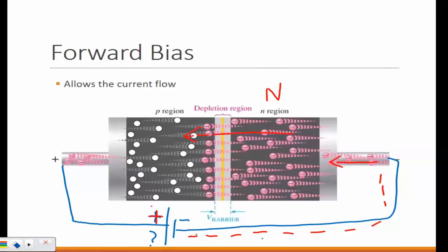Again, you can have a full current if you have at least 0.7 volts, because that will counteract the already developed barrier potential of 0.7 volts. Then you can operate it for whatever application you want. Again, we're only talking about how to use the diode at this moment: how to forward bias a diode, and what happens. The applications are coming after next class, when we will start applications. If diodes conduct current, what can I do with it? That will come later.